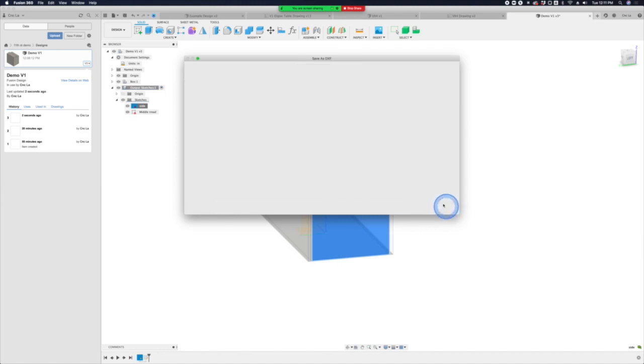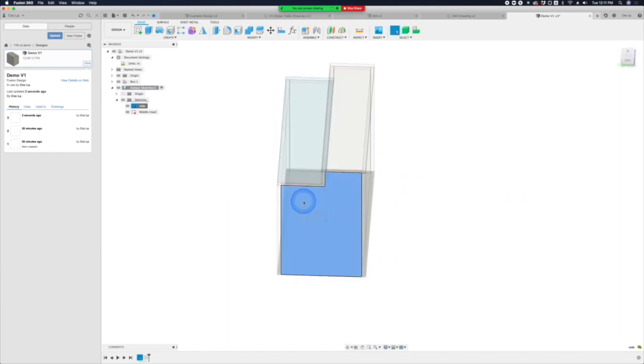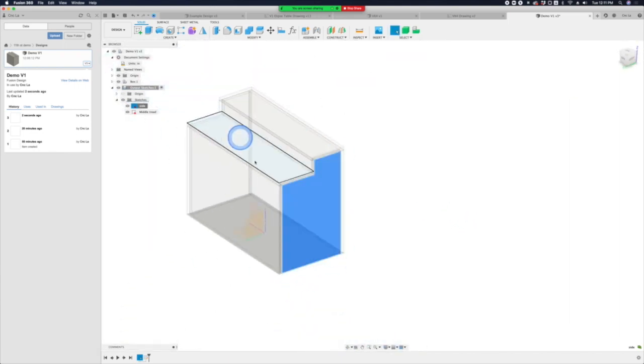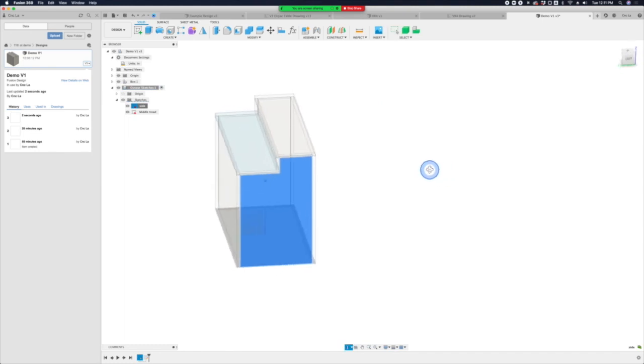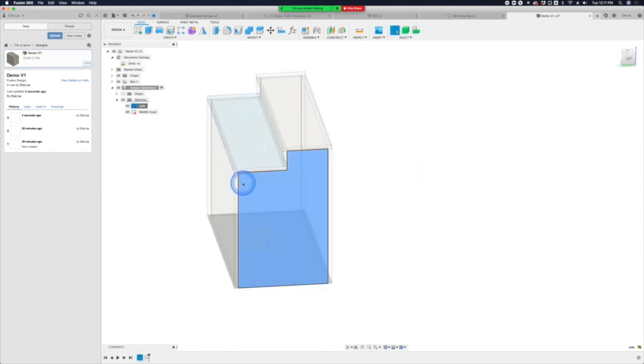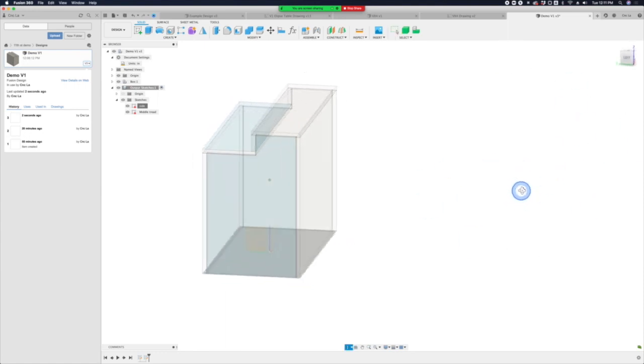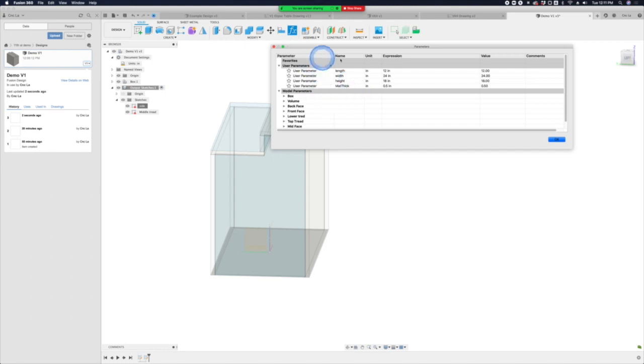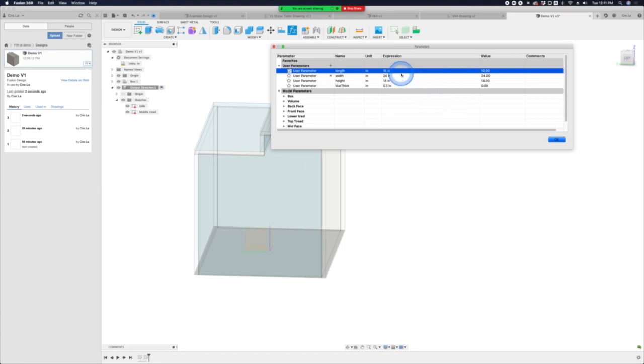The reason I like to do that is because construction lines show up in the DXF. They may be dashed in here, but if you have lines helping you define something in there, they'll show up in the DXF and the operator can get confused about what all this extra geometry is. But then I like this because if we change the length, let's see if this works this time. Kind of, yeah, basically.